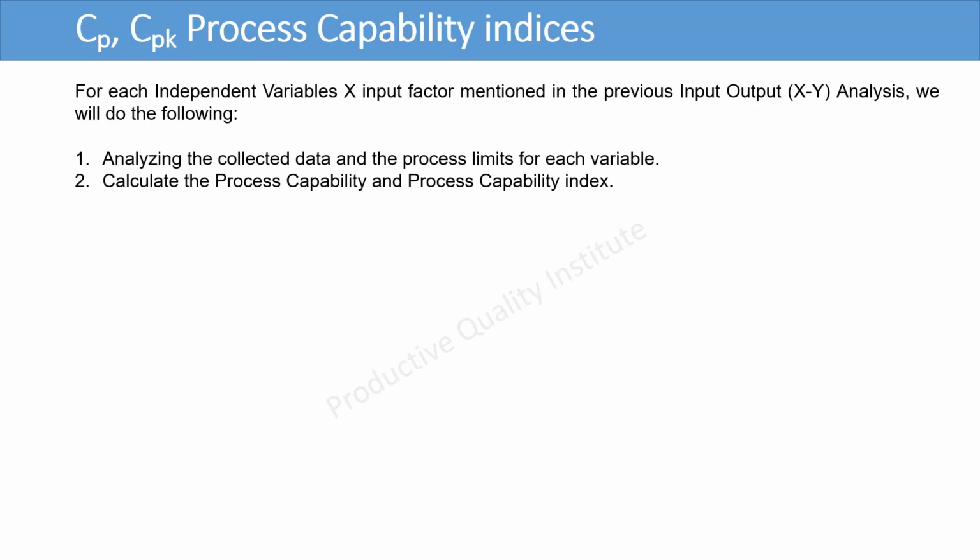For each independent variable's X input factor mentioned in the previous input-output XY analysis, we will do the following. Analyzing the collected data and the process limits for each variable. Calculate the process capability and process capability index.